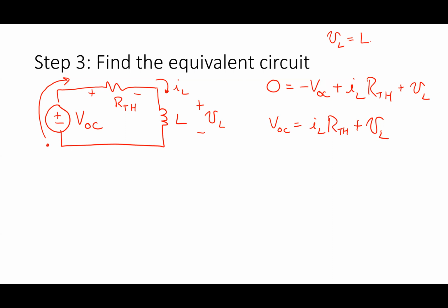L times... Yep, dIL by dt. Yeah, good. All right, so now I got a differential equation, right? This is first order. IL times RTH plus L dIL by dt.